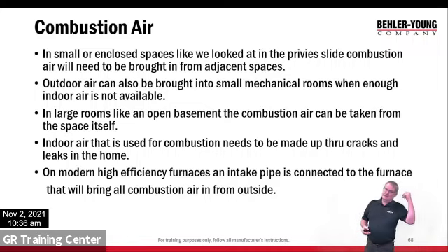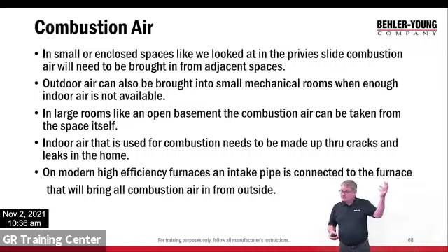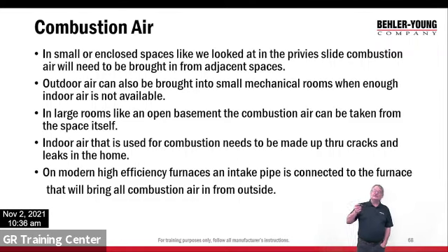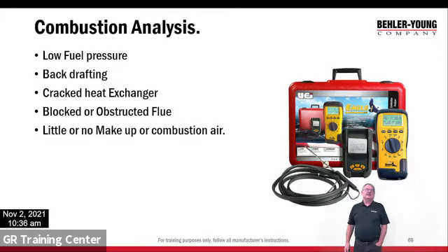Water heaters, a gas dryer requires combustion air as well. So the calculation can be the same. We still have to make up. So now we've got the furnace plus the water heater plus the dryer in the same room. So we need to calculate the combustion air for all of them because they all need it. Okay, so again, on the modern high efficiency furnaces, we're bringing the air in specifically for combustion. So we will talk about that here in a minute.